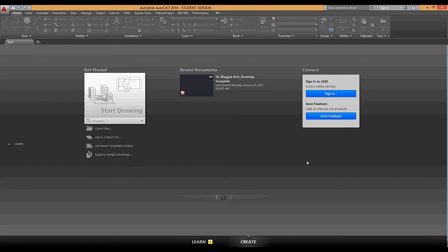As a simple example, it's advisable in a floor plan to keep different categories of objects on different layers. That could be walls, furniture, plumbing fixtures, doors, notes, etc. So you can display or plot them as required, depending on the person you are preparing the drawing for. The client in general needs to see different information than, for example, the mechanical engineer. Layers allow us to sort that information as opposed to creating multiple drawings with that information. We'll be getting into more advanced aspects of layers in later classes as we use them more.